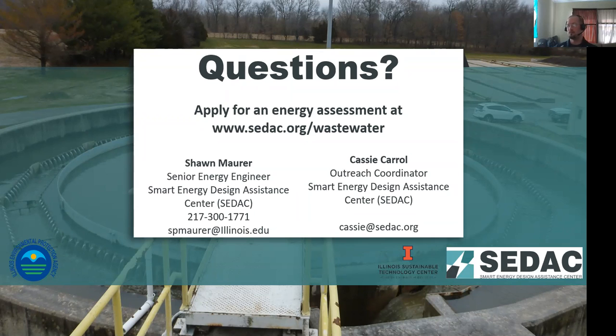Energy monitoring can help identify problems in a system. Long-term tracking can help track whether your process is slowly increasing in energy use. If you see a sudden jump, you know to go out and look for some kind of mechanical failure. If you see a sudden drop, might be the same thing. Something may have dropped offline. So energy monitoring is a great way to track the performance of your system over time. And I would recommend it if you can do it.